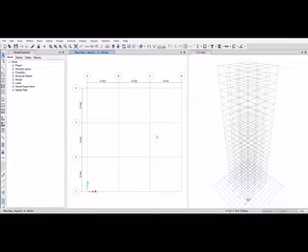change the dimensions 500 cross 500. For reinforcement properties, select modify/show rebar, change the longitudinal bar to HYSD 500 and confinement bar to mild 250, and cross check the clear cover for confinement bar is 40 mm and click on OK. Click on OK again. So the column of 500 by 500 section has been defined.